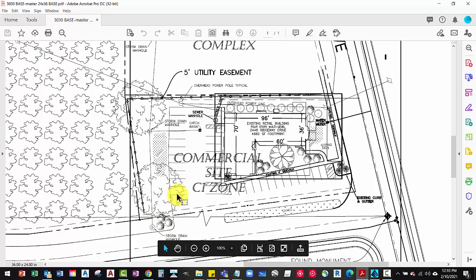Now, like for these big trees, you can pull in that civil or trees drawing that I've provided for you, insert that into the drawing, into your topo map, and then you can just copy or insert the actual trees right over top of where the point is. So there's a point that's going to be representing where the tree is, the center line of the tree.